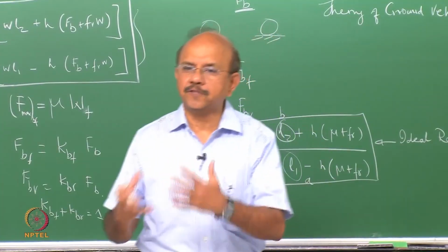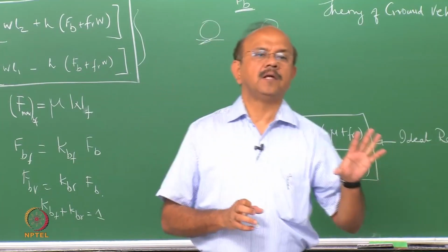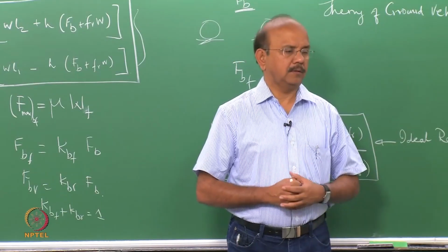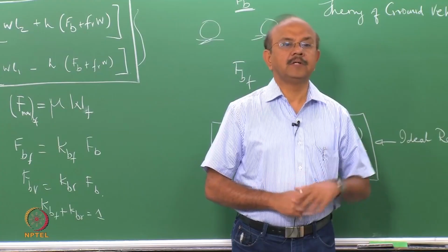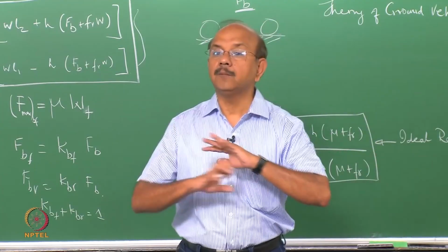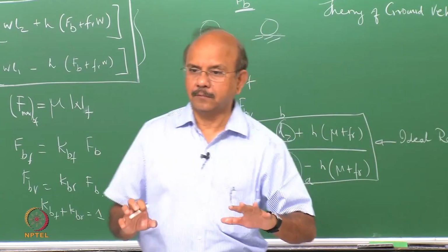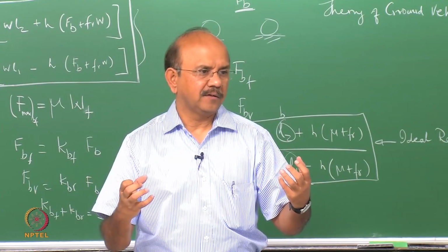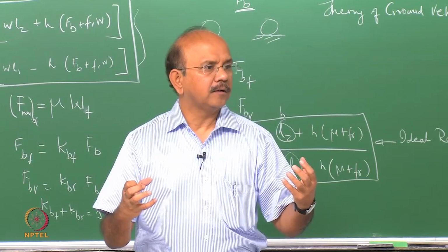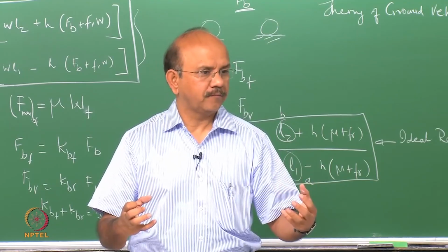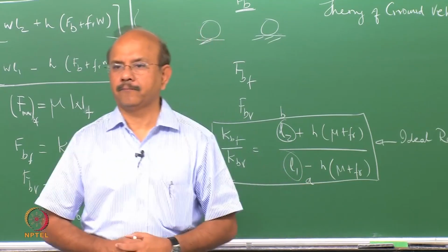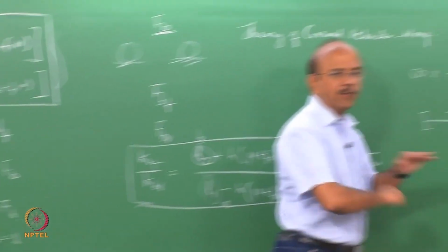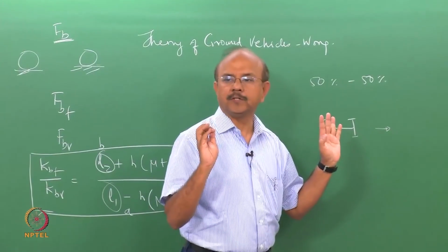What is meant by locking from the physical principles? Locking simply means that all the mu that's available for that tire has been completely consumed. So no more of that friction factor is available for any other force that acts on that wheel. Let's assume that the rear wheels have locked, all mu has been consumed.